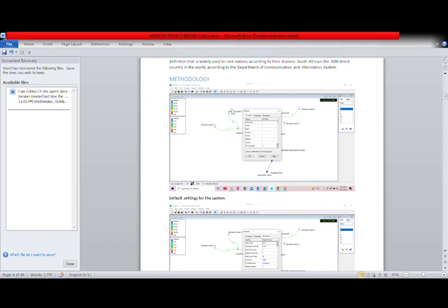This is where you go to hydraulics, and this is where you set the standards for the calculations, as well as the units for what you'll be doing here. So we know that since we have been given liters per second, I've changed the flow units to LPS, which is liters per second, and we'll be using the HW formula in order to get the calculations right.